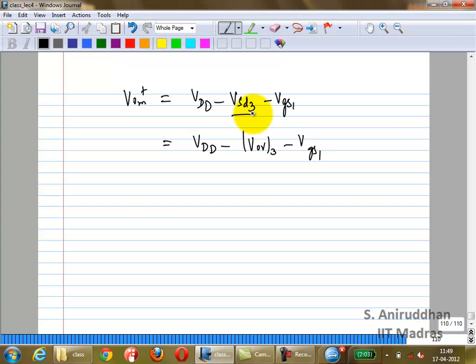Okay, so what else? Can you do a common source? Yeah, you can. In this case, we have just looked at class A, class AB, class B with emitter followers and source followers. You can bias a common emitter or a common source in a similar format. In fact, the original archetype we looked at on the first day when we started off output stages was a common source amplifier with a current source. If it's biased at VT, it is class B and so on. That's what we decided. Right? So what we did was the case with emitter followers, but in reality, any kind of amplifier can be used in these different modes, depending on how you bias it. Okay?